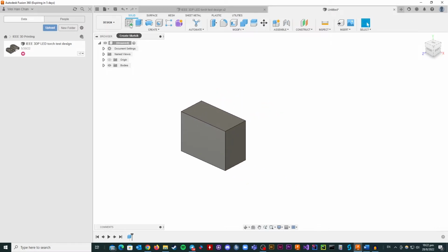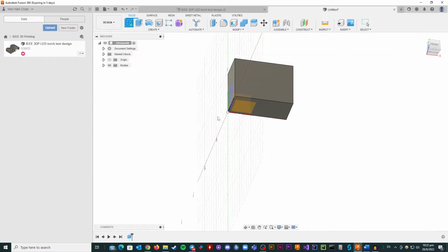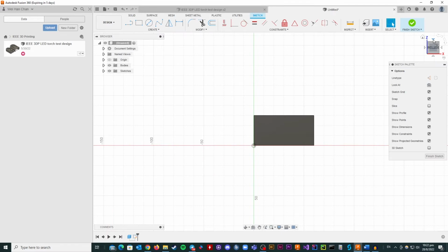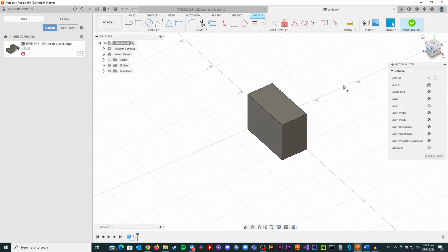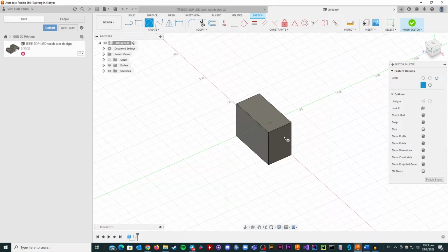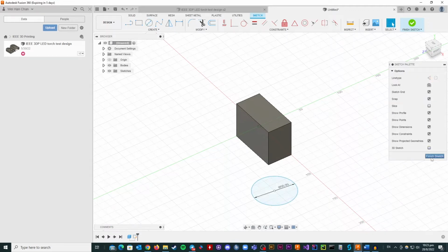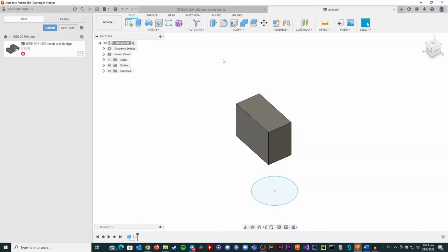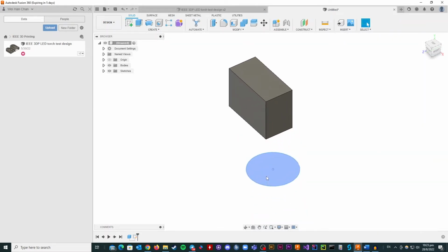Now we'll also do this the other way. We can start by creating a sketch. Of course, we'll select the same bottom facing plane that we want, and get this to the right orientation. Let's say we want to start with a circle instead this time. We find a starting point, let's select this one, and we set the diameter to be 50 millimeters. Now you can just type 50, it'll be the same. Finish sketch once you've gotten your circle or your shape in.